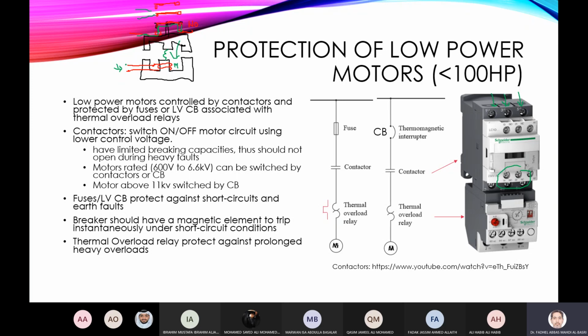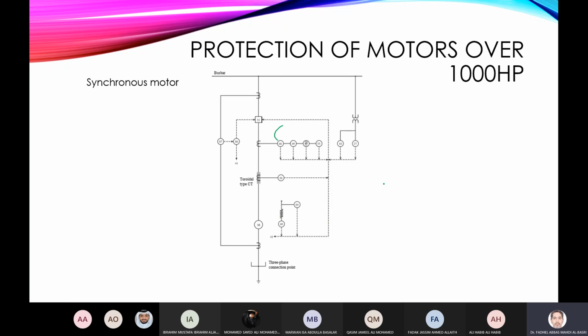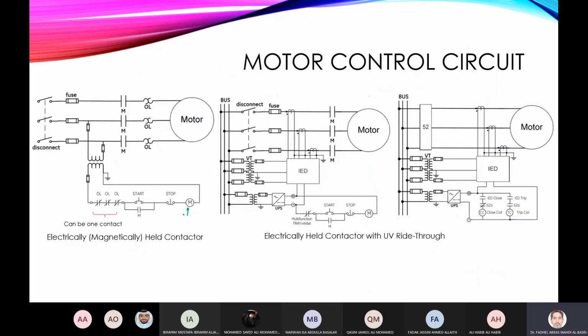And normally in a contactor, the terminals of the coil are A1 and A2. And to know where the terminals of this coil are, this is normally standard. The terminals of the coil are A1 and A2. So if you energize this A1 and A2 with a voltage, these contacts will close and supply the voltage to the motor to start. So how do I do this?